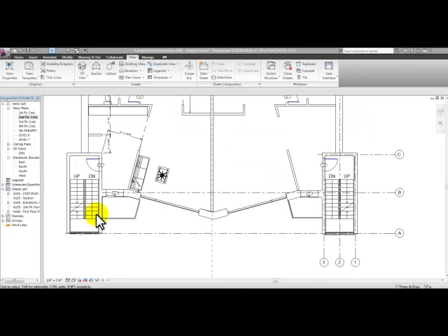Use the Tab key to cycle through objects that are close to the location of your pointer, and also if you rest your pointer on one wall and use the Tab key, the chain of walls will be selected once you highlight them and click.